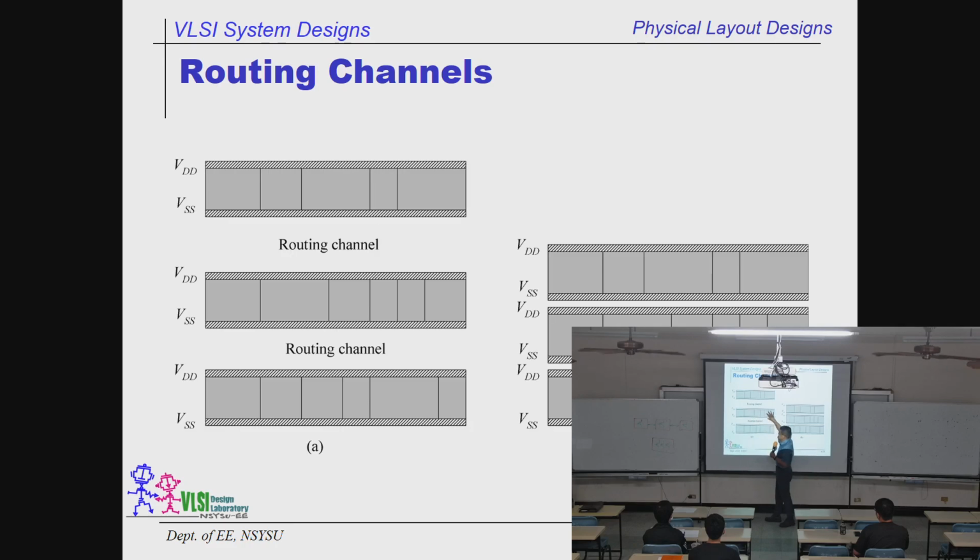So we have a group of cells sitting together on the top. They do a lot of processing over there. We have another group here. They also do a lot of jobs to process some signals flowing in these directions. And some control signals, they should share together. And we need some space in between. It's called the routing channel. The channel is meant to draw these control signals over here. You can consider this as a free space.